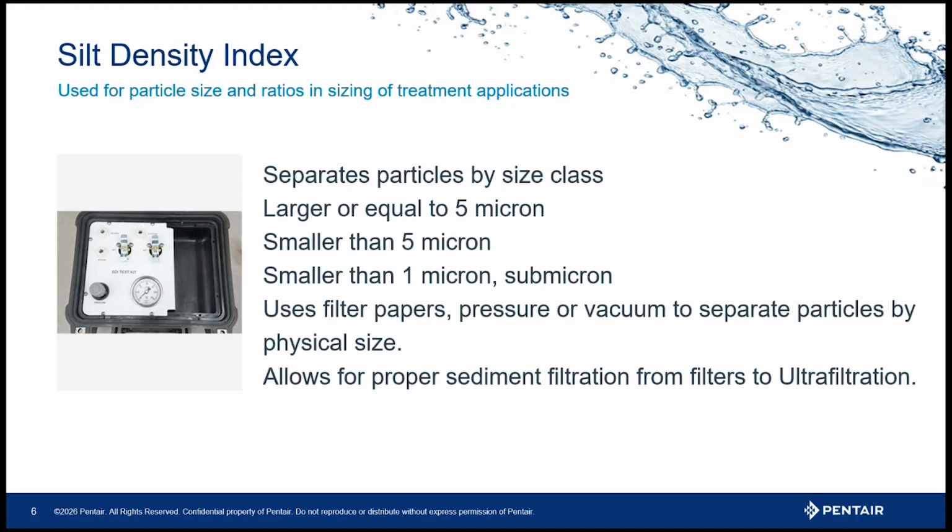Acidify that turbidity sample and retake the test. See how much color is left. Any turbidity left after that test is going to be organic in nature. Take a new raw water sample if there are organics present and test it for tannins, so you can dial in whether it is a process you want to follow specifically for tannin removal.